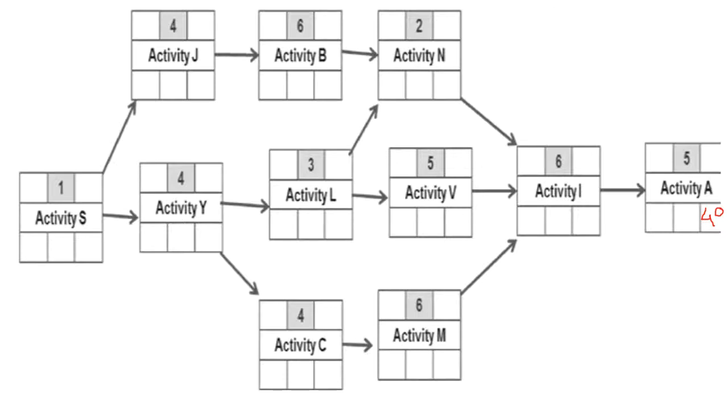So in this project, rather than starting from the front, as we saw in the normal scheduling activities, we are starting the scheduling from the constraint point, which is the day 40 of the project. So basically, we will calculate the late start of the activity and go in the reverse direction.